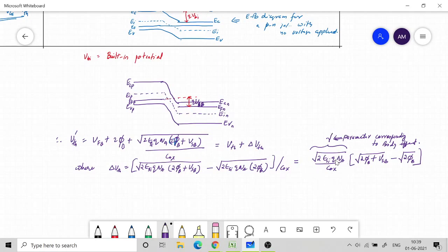And this expression here for gamma is not very accurate, but this is a very simple way of deriving it. Actually this gamma is estimated from experiment. Okay, so when you apply the potential, you find out from the characteristics how much the threshold changes, and then take the appropriate value of gamma and substitute it in the model.